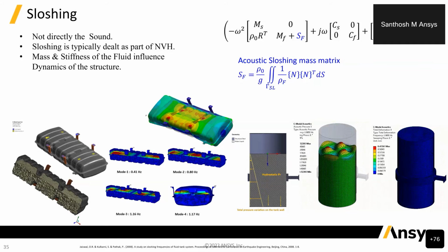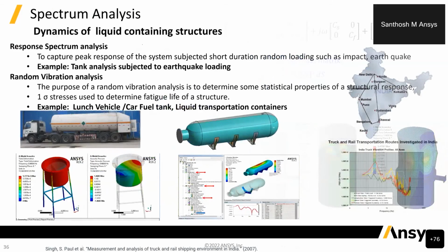Because of this fluid sloshing, the vibration shapes and the stress on the structure are going to change. Those will impact the durability and life of the structural components as well. Those can also be studied using the same technique.